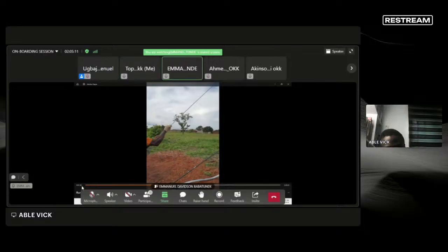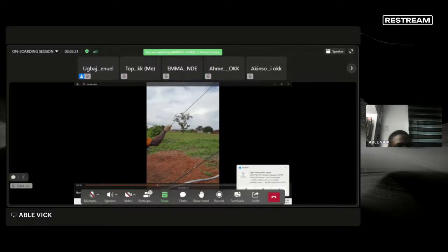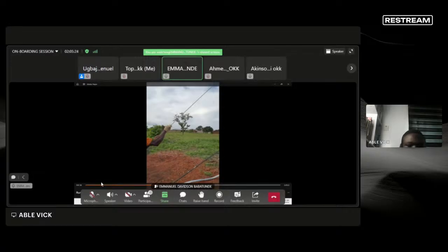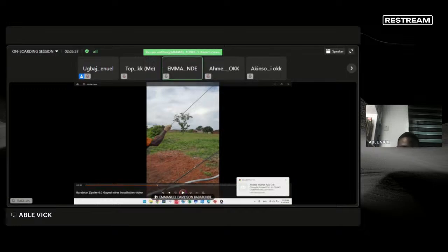If your backfilling material can achieve the compaction density, that's laterite. If your material is laterite, then after compaction, if you go back to that site 1 week after, it's a digger you use to excavate the material out. If your material is that kind of material, we're not supposed to have issue. But if your material is a loose material and you're using it to compact, you're on your own. So you also need to check the kind of material you have on site. If it's not suitable for backfilling, you need to escalate.